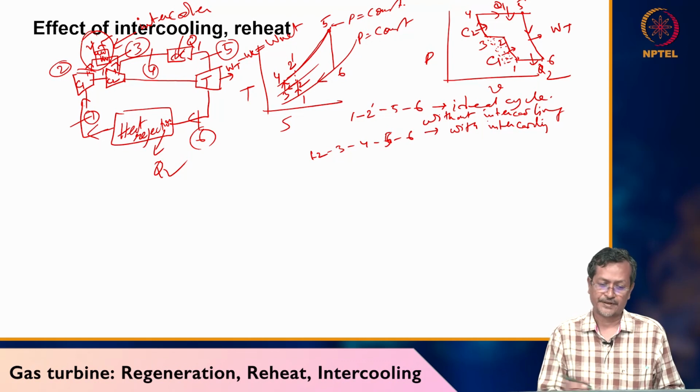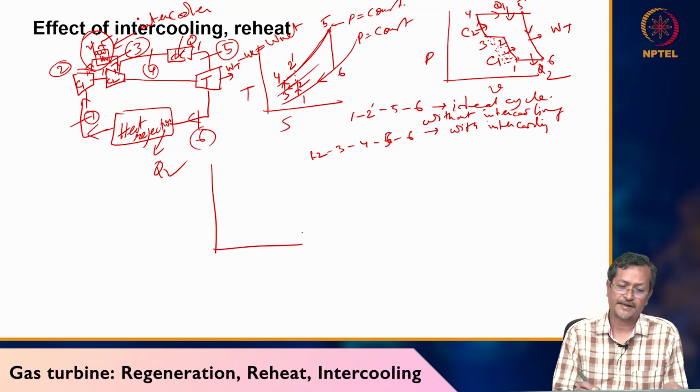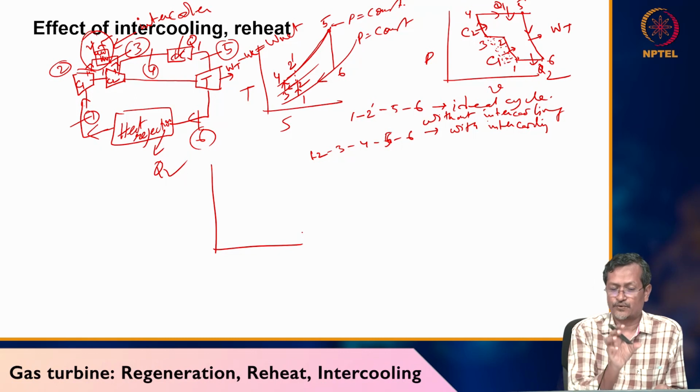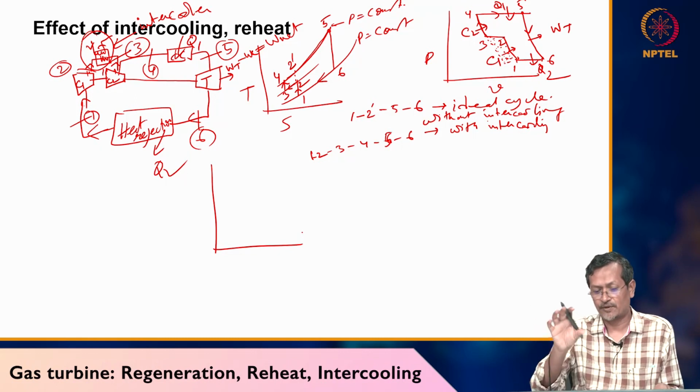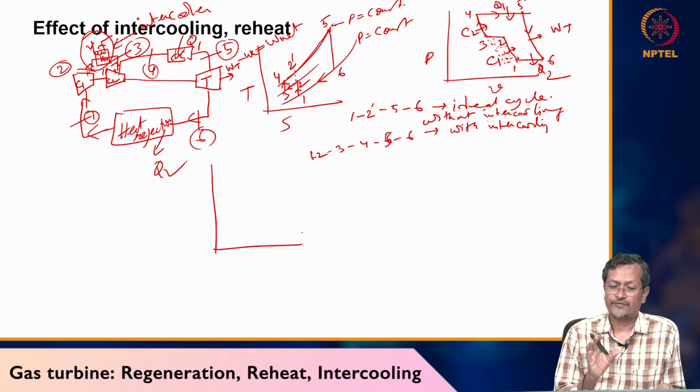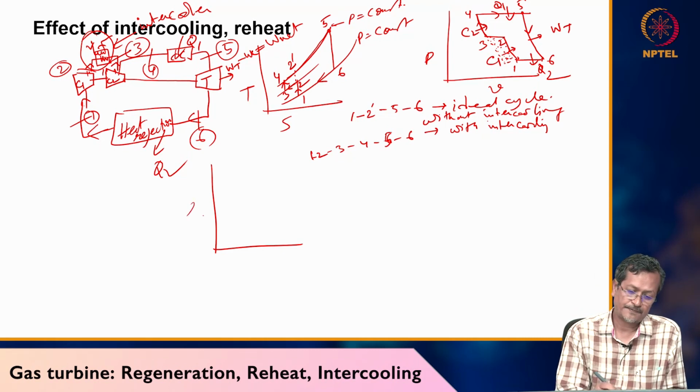Now, what is the purpose of intercooling? Let's say I have multiple stages of compressor: compressor 1, compressor 2, compressor 3, compressor 4, many compressors. If we have many compressors, we will be trying to achieve our isothermal condition. If we have an isothermal system, that will have the best efficiency. Okay, the whole system. So P, V, and let's say this is my system.